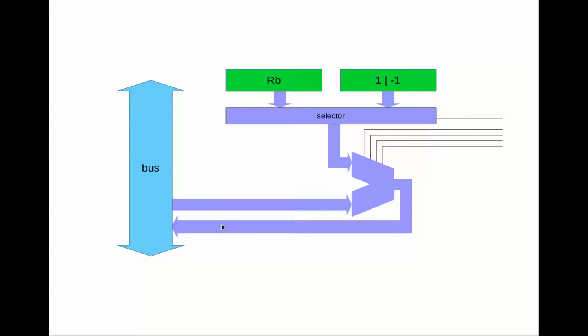But of course, this design isn't really going to work because we have two components, one of them reading and the other one writing directly to the bus. And as we saw when we talked about registers in that episode, we can't do that, because if some other register, let's say we have the A register up here, is outputting its value onto the bus, well then the ALU can't be outputting a value at the same time.